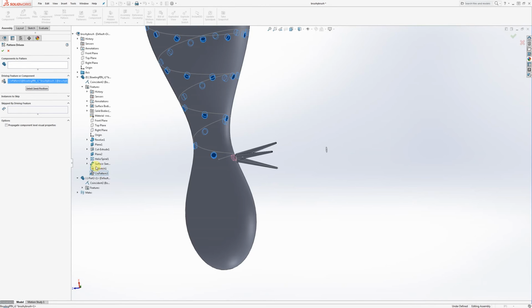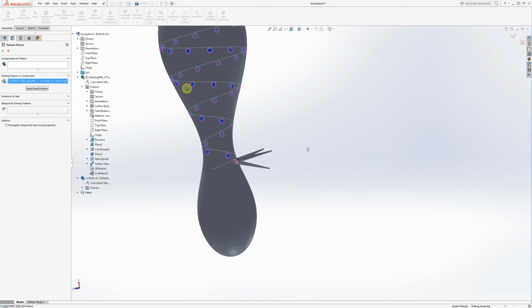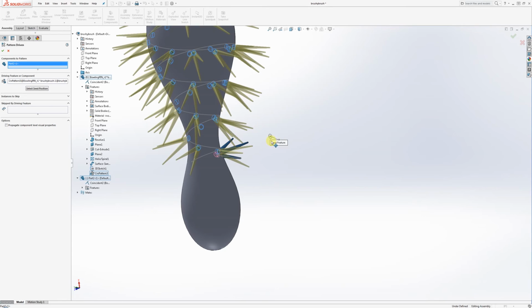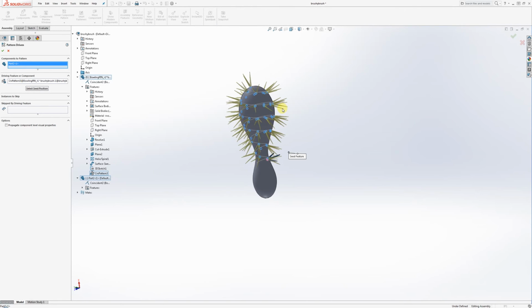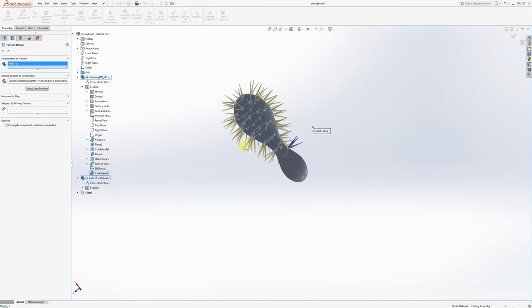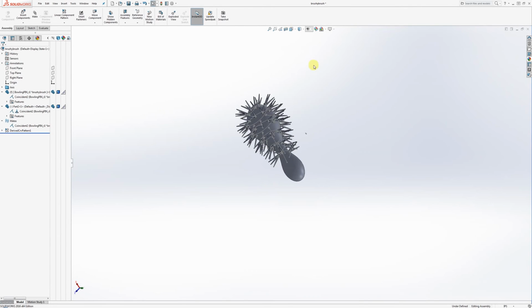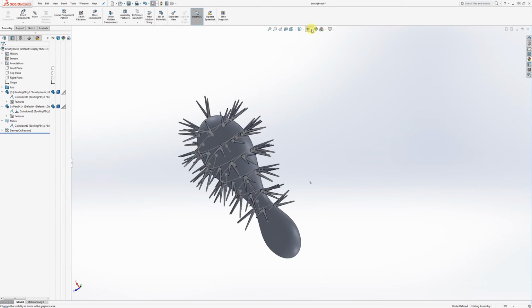And this should do the trick. Component to pattern. There you go. Sometimes it loses itself there. And that's that. Okay, so now it's using the pattern from the brush body to run a component pattern of that. Voila. Cool. Now there's a lot of stuff getting shown here, so this is where this look at command can come in handy, right? You can show to hide sketches, and now you get just that.